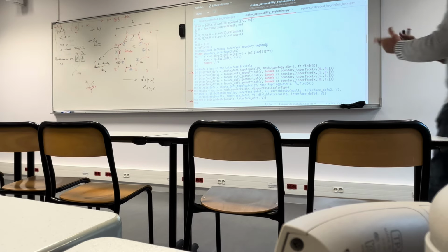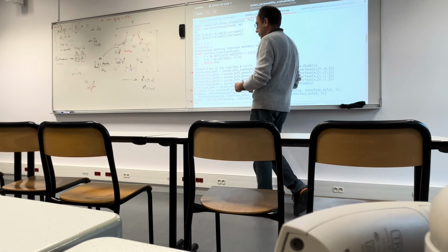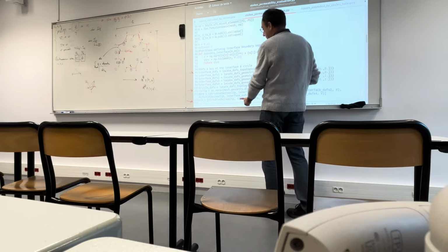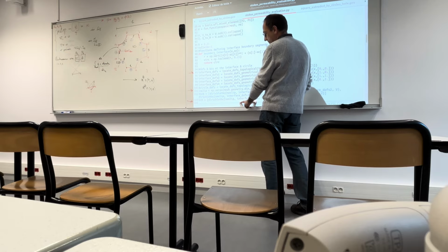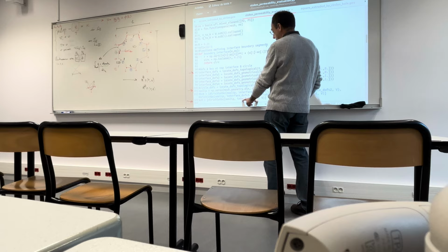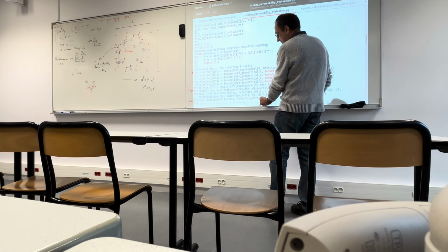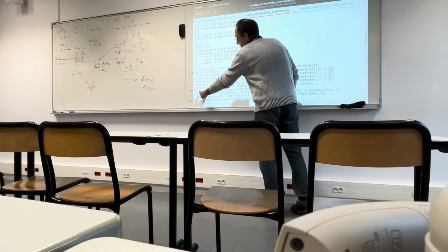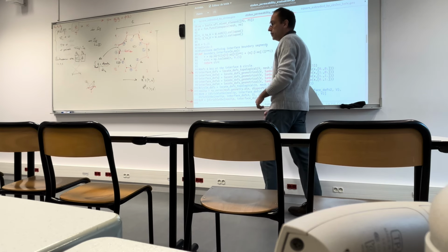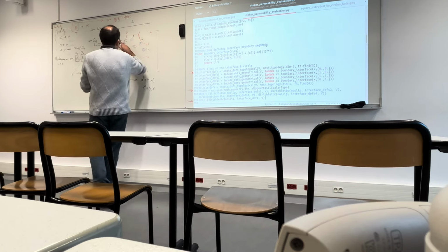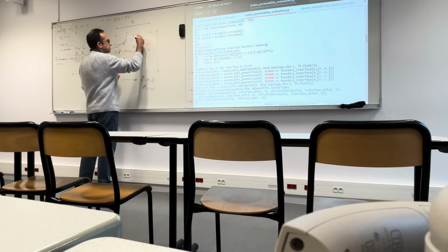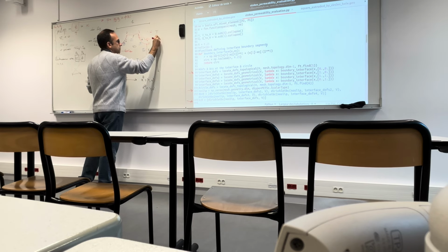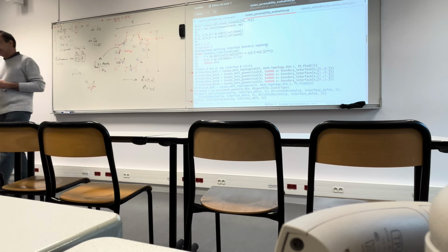Okay. So obviously there is a certain amount of syntax that one should learn, but the meaning is reasonably clear, in the sense that you have to specify what are the degree of freedom involved in these Dirichlet boundary conditions, to what space you are referring to, the velocity, and what is the prescription. This no slip is just a vector of zeros. So you are saying on all these points v equals 0, or if you prefer, v1 equals 0 and v2 equals 0. Okay? This is what we are saying.